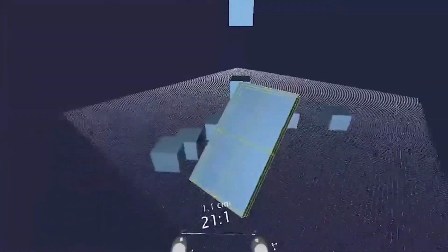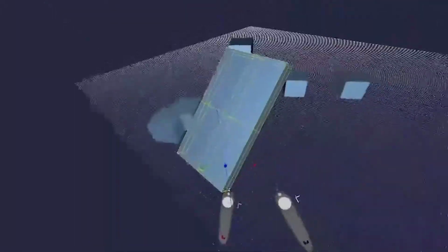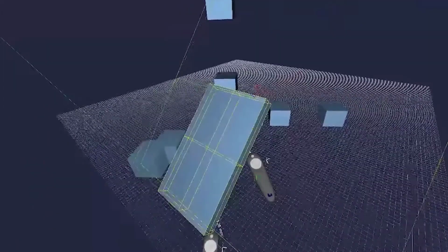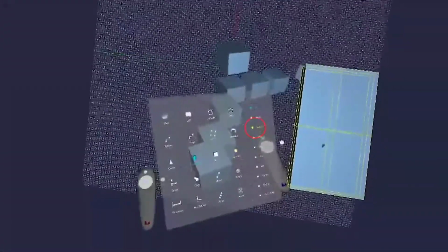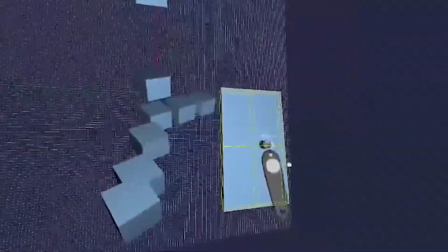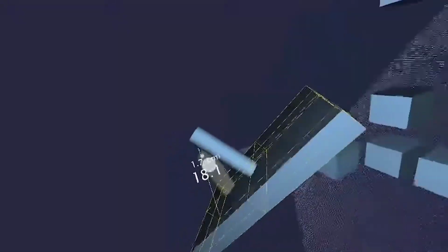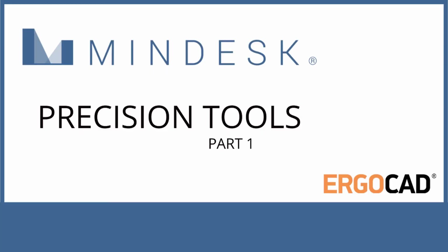In fact, you can also adjust the reference plane to be at a diagonal, not just a rotation in the vertical. So using the same command again, I grab the base, rotate up to the box, and now the grid will be in the same reference as this new box that I've rotated. So making sure that my near surface snap is on, any new geometry like the cylinder or a box lets me freely model on that same C-plane without any issues.